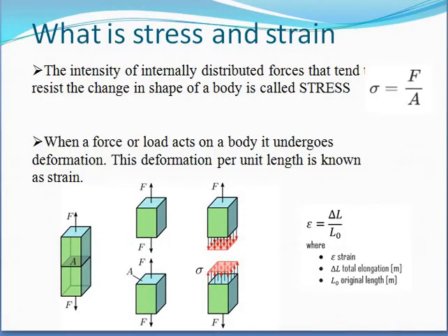Let us start with the basics. What is stress and strain, which you have already studied in your third semester mechanics of material subject. Stress is the intensity of internally distributed forces that tend to resist the change in shape of a body. Here in the figure you can see that a member is subjected to a tensile load. So here you can see that the stresses are developed internally to resist the deformation. This is called stress, which is calculated as stress is equal to load divided by area.